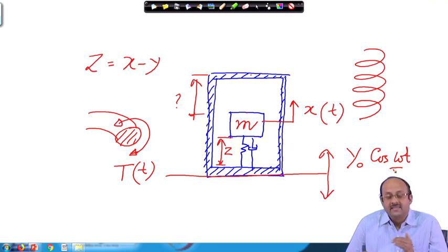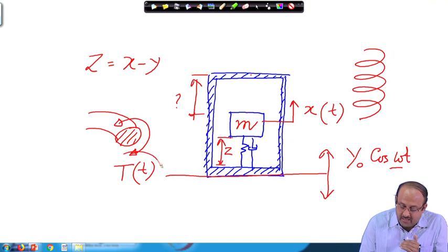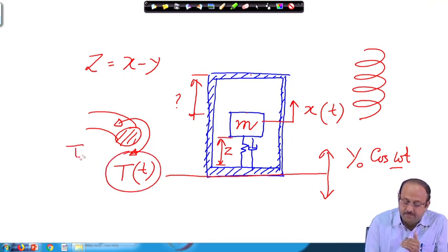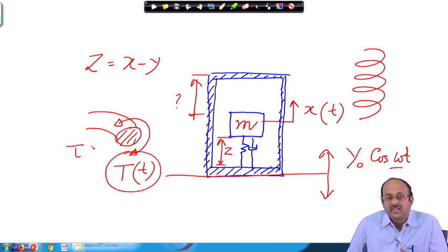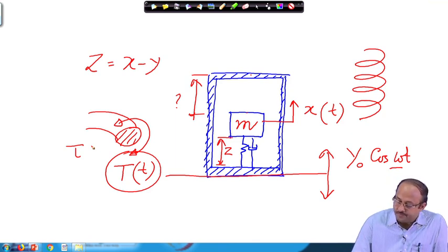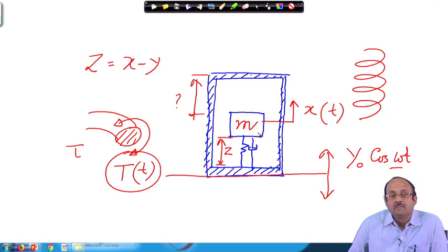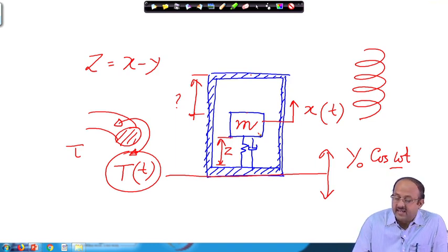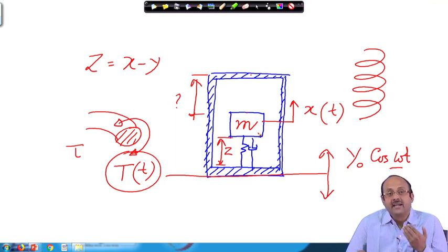That means, the torque will develop shear stress in the spring. This shear stress will be fluctuating. Now, if there is a fluctuating stress, then it may so happen that the material can fail because of fatigue. Also, it may so happen that the displacement or the deformation of the spring is so large that it can reach the ultimate breaking stress, and the spring can also break.